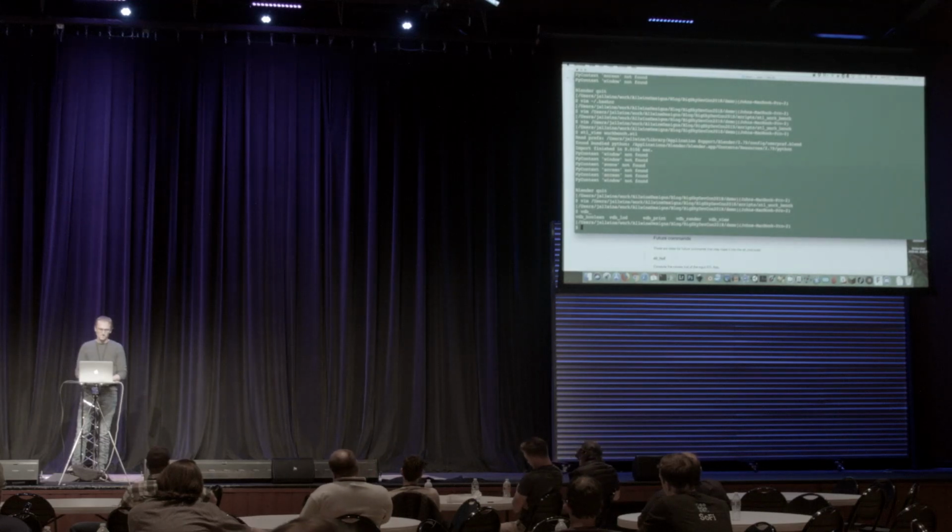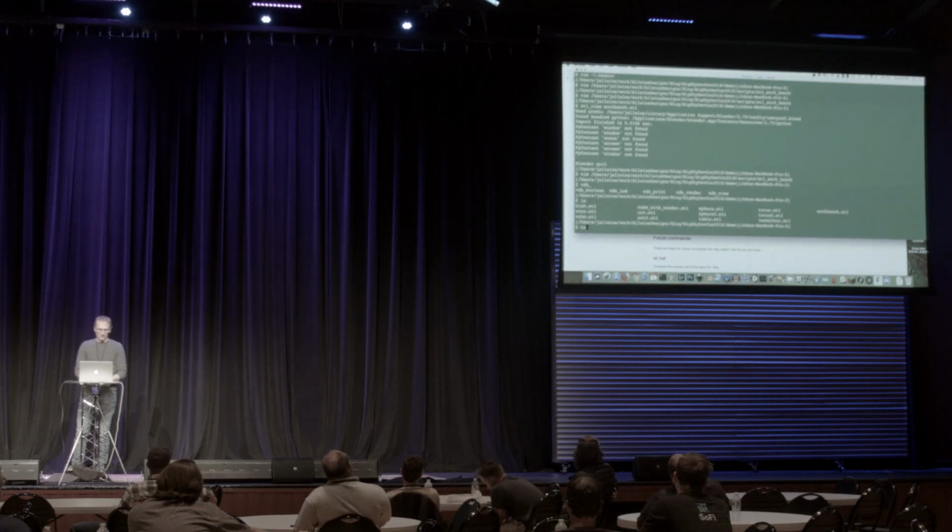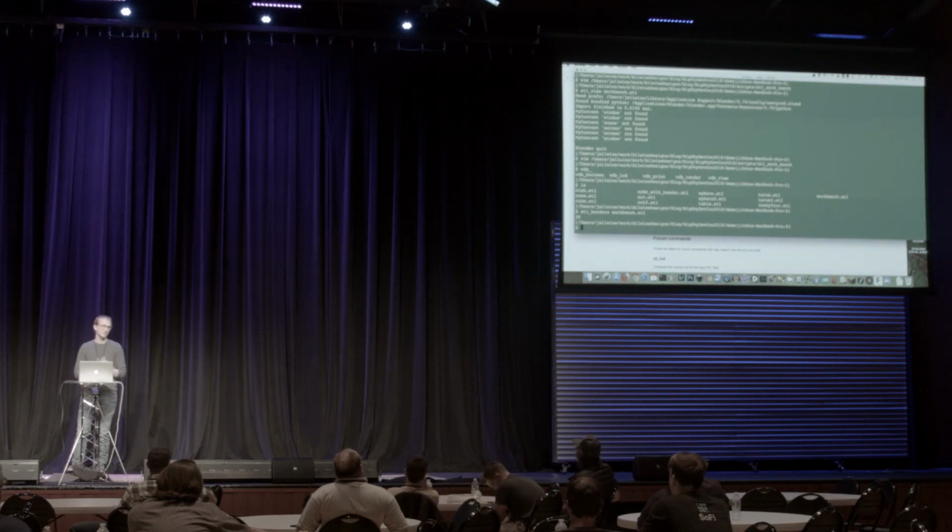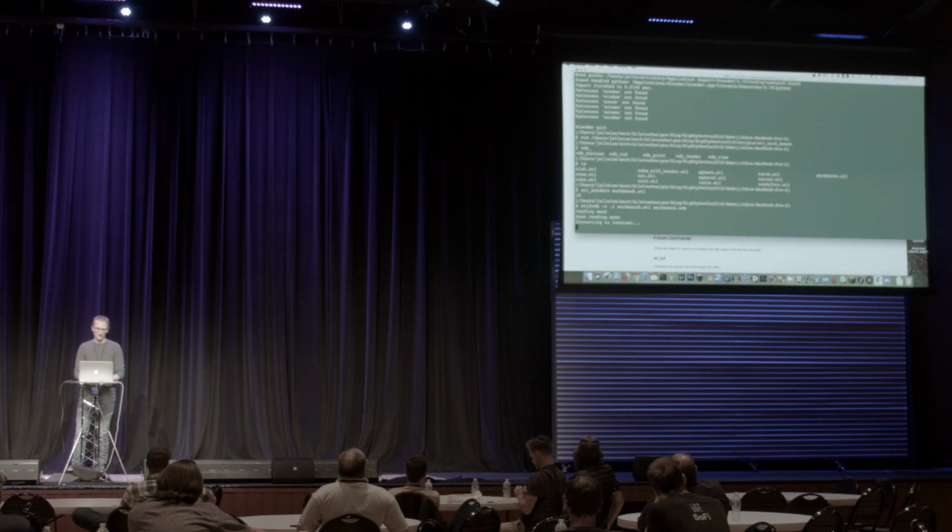And there's an STL to VDB command. So let's see, stl borders workbench.stl. There are 36 problem areas in this, so holes in my model. I don't know where they are, but I'm going to run STL to VDB. I'm going to rasterize this into a voxel format. So I'll set my voxel size to 0.1. Hopefully this will finish. I don't know if this will work. Into workbench.vdb. So it's converting it.